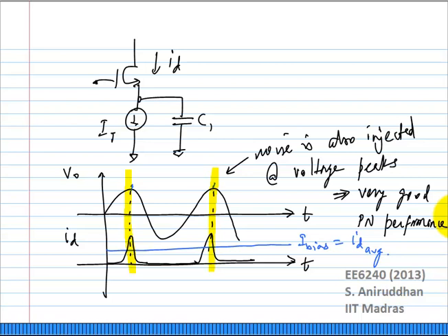Now the funny thing about the differential version is that it actually used a cross-coupled pair to make it differential. Okay, it's quite funny. So that is what they needed to do to make this differential. And what people have found is that this does have slightly better phase noise. Unfortunately, it also has much lower tuning range compared to the normal cross-coupled oscillator.